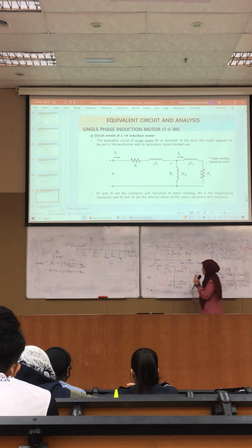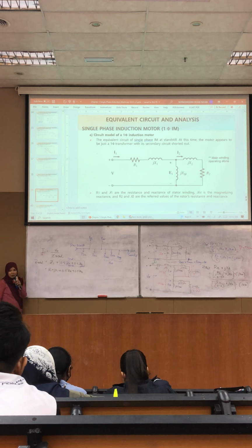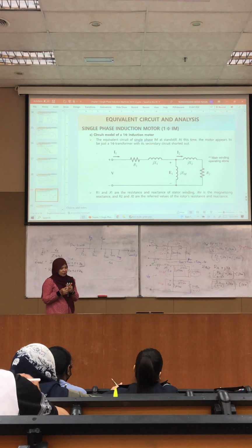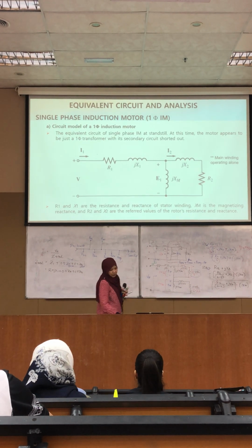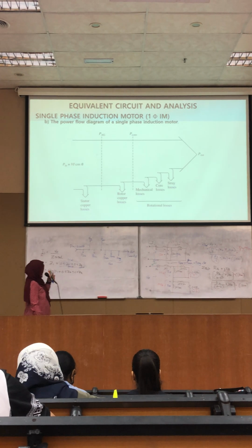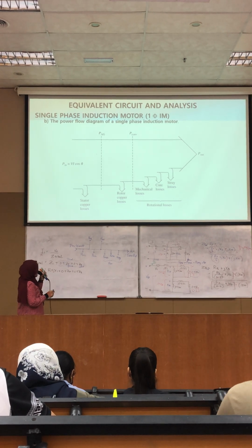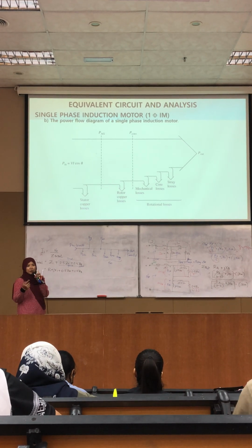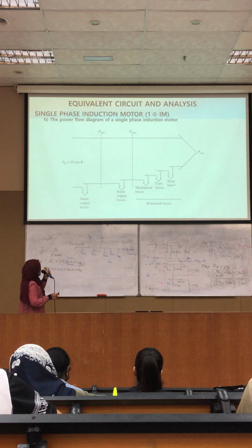Okay, settled, we know how to find the Z total and we can find the stator current. Why do we need to find the stator current? Because we need to find the losses. Already mentioned, this one, the losses. Same as before. What else? The difference is we don't multiply by 3 because it's one phase. Nothing else, the same. Maybe just the arrangement of this one.